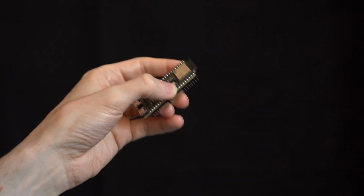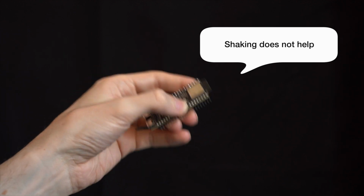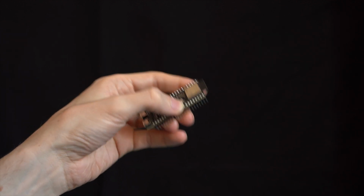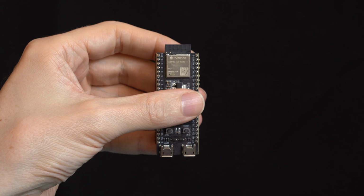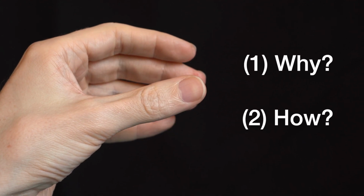You can completely stop the clock from drifting if you prevent the chip from sleeping. But that is not a good option when your project is powered by a battery. So I wondered, first, what causes the behavior, and second, what can you do to fix it?